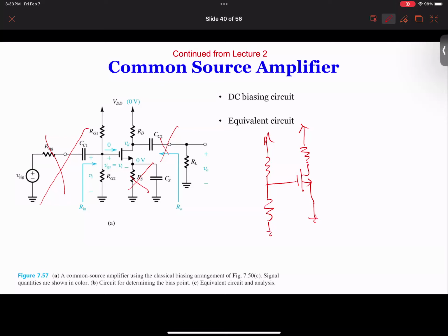So for DC biasing, you get a DC voltage here. There's no current in the source. Therefore, these two resistors become a voltage divider. You can easily find the voltage at the gate, and from that, you have VGS. Now, knowing VTO, you can find the gain gm. The transconductance gm is equal to, not 1/2 here, K W over L times (VGS minus VT). So that's how you get your gain. You're done with your DC biasing calculations.